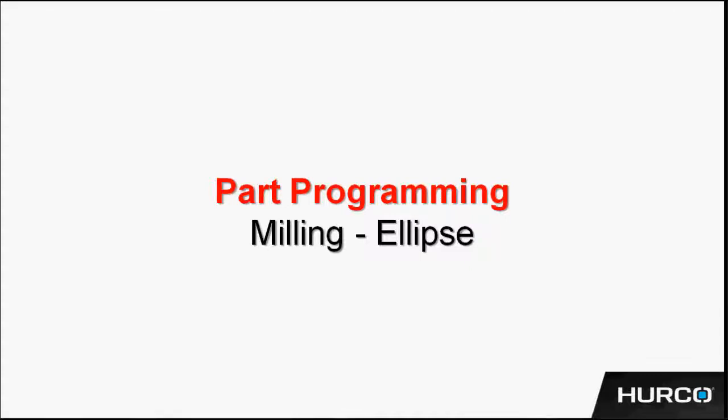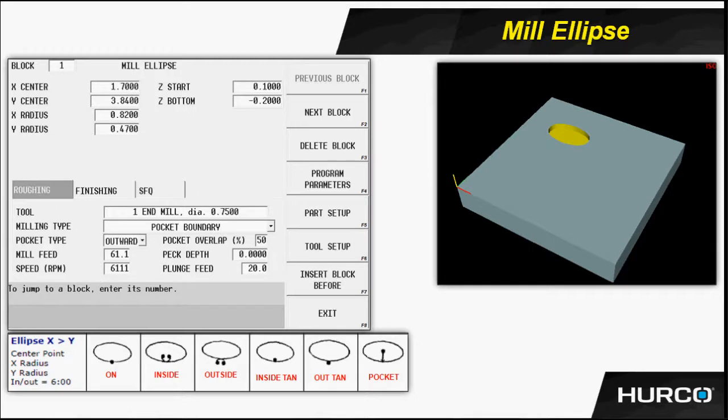Okay, let's talk about mill-ellipse. Let's add a mill-ellipse to a program. Here we see the ellipse block. It's very similar to the circle. The only difference being the circle asks for one radius. The ellipse asks for two radiuses, one in the x and one in the y.